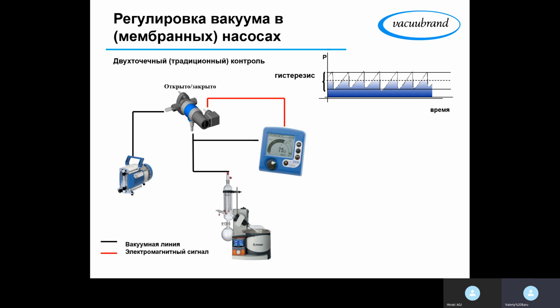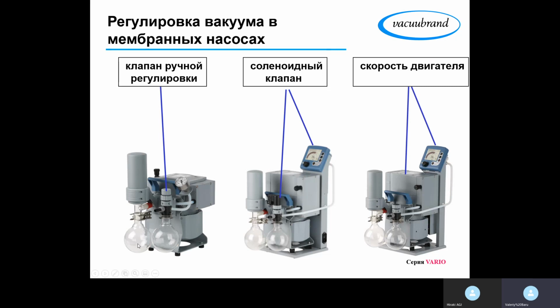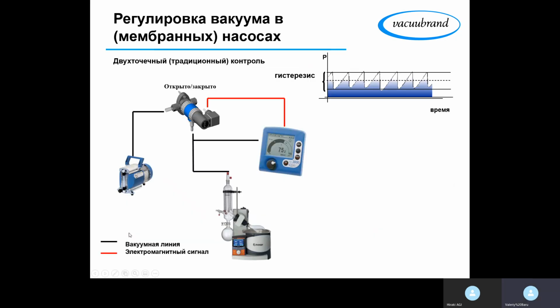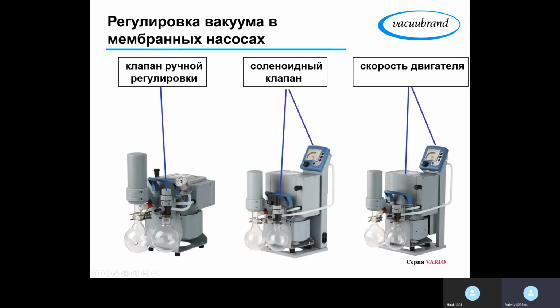Okay, never mind, you got the idea. So the amount of solvent will be collected not in the receiver of the rotary evaporator, but in the receiver on the outlet of the vacuum pump. In this case, we will have some problem because we will have some condensate here and some condensate in here.